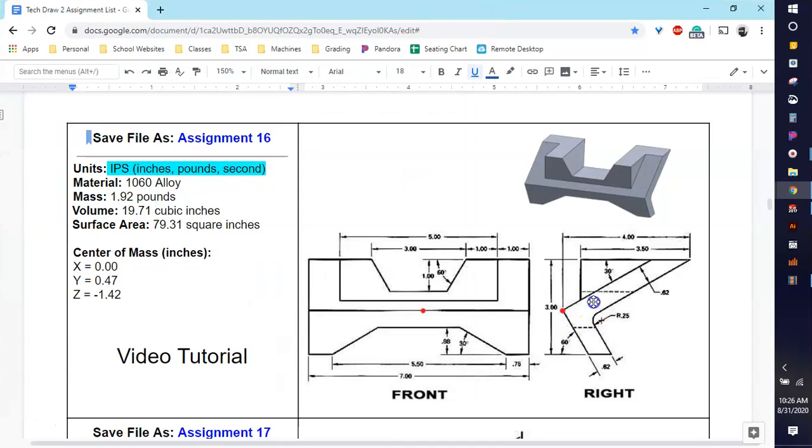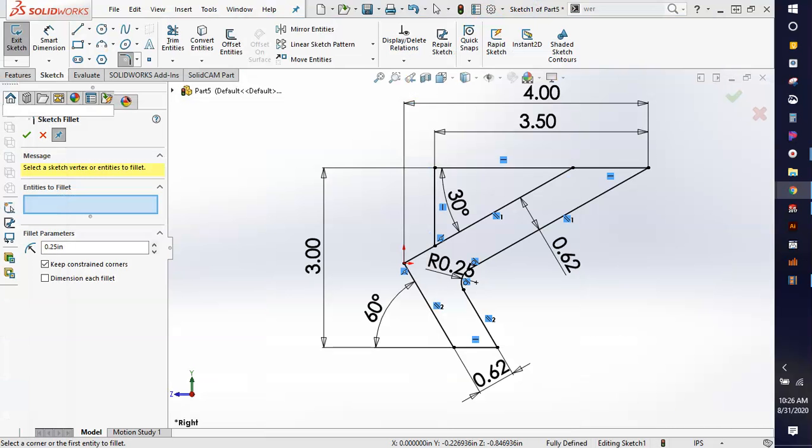So these little dashed lines there and there, those are hidden because this line is indicating the bottom of this cut out in the middle, and this hidden line is indicating the top of this cut out of the bottom. Okay, so this piece and this piece here. So we don't need to draw those right now because those will actually come naturally later on.